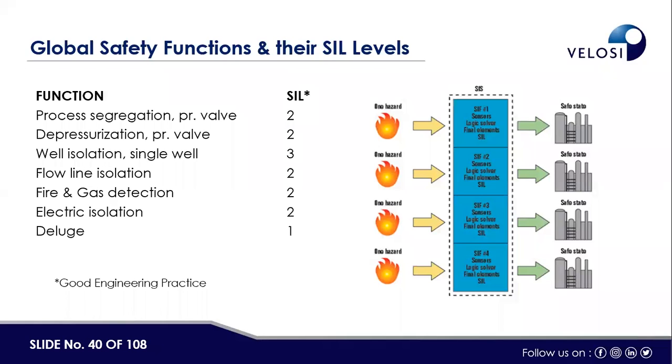And similarly, the Norwegian oil and gas industry also identified minimum SIL levels, which should not be reduced by the analysis process, even though you can have both a minimum SIL level determined by the SIL study process and then a target given by the standard.